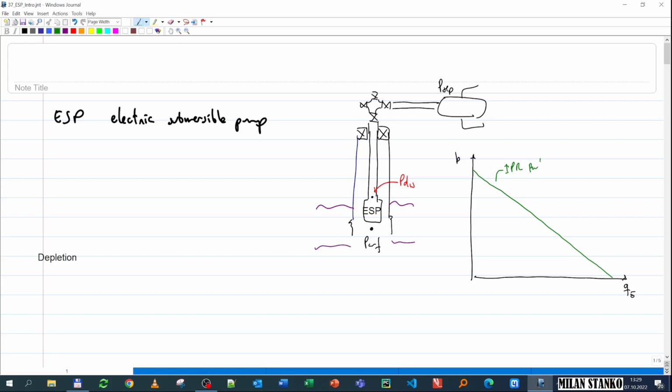And then I'm going to plot also the required pressure curve, which is the pressure that I require to flow against separator pressure for different rates and when flowing exactly at the discharge of the pump. So that curve looks like that. Okay, this is my TPR, and this is for a constant wellhead pressure. So if I assume I put these two systems together with no pump, then the rate that this well will produce will be this one, Q oil star.